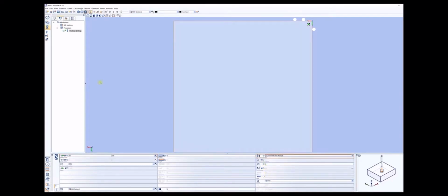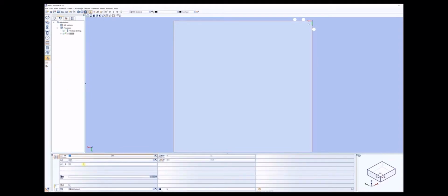Next, click on the Collection Macros icon and then the block macro. Your X and Y position will be 0. Your coordinate system will be 0. Your Z position will also be 0. If you had a block you wanted to load, you could do so here. If you wanted to save this file as a .blk extension, you would click on Save once you have completed this. This checkbox here is to optimize your components.